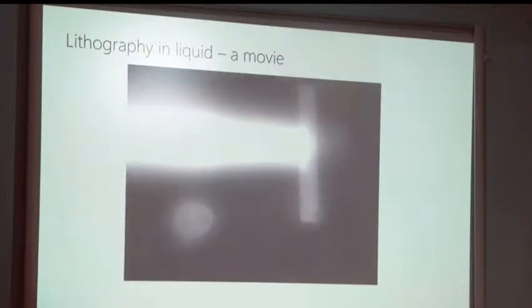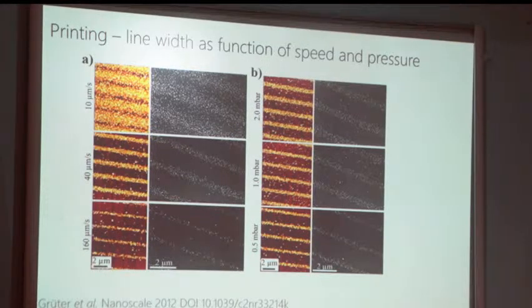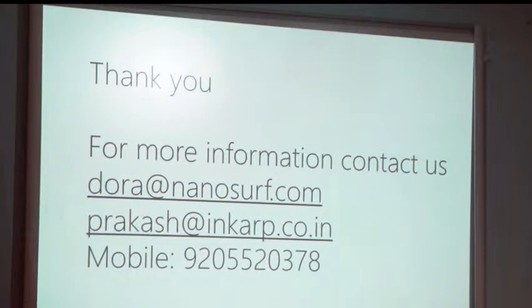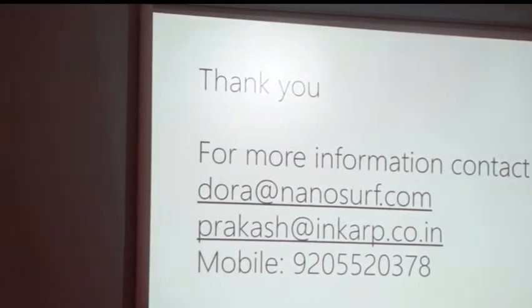And once it is done, you can always take a picture, and by controlling the process, you can have nanowires of different widths and sizes. So those things are also possible using an AFM. This is more or less an overview of what you can do using AFMs and what is unique to NanoSurf. I have not explained all the details of individual modes, which are more theoretical, or which need more information on how to do these experiments. But this is an overview of what an AFM is capable of.